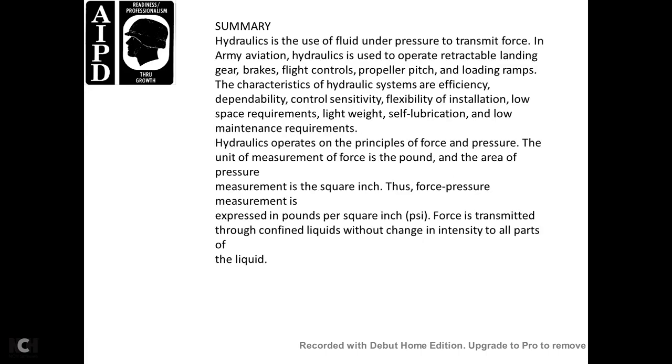Summary. Hydraulics is the use of fluid under pressure to transmit force in Army aviation. Hydraulics is used for the operation of the retractable landing gear, brakes, flight controls, and the proper pitch for the loading ramp. The characteristics of the hydraulic system are efficiency, dependability, control, sensitivity, flexibility for installation, low space requirements, light weight, self-lubrication, and low maintenance requirements.